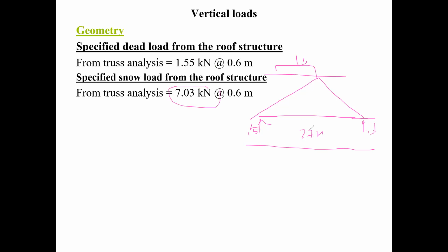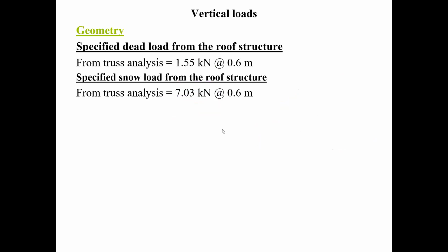But I said, I've already done all the work. The computer program is going to give me the value, and there's my snow load. Now don't forget, this is 100% snow load, so this is good for load combination number 3. When I'm doing load combination number 4, I will take half this value. That's all it is. That's how I take advantage of ADA to simplify my life, because it does the analysis for me and gives me my results right away. So clear all the drawings, and now the specified loads. Now, of course, the exterior wall also carries